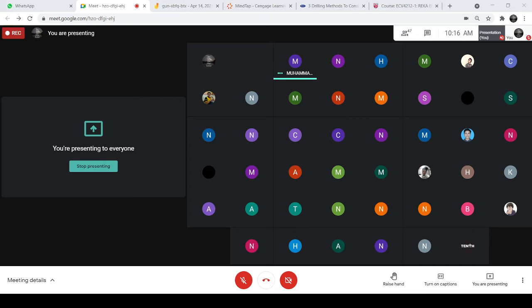The outside diameter is 66.68 millimeter, 82.55 millimeter, 101.6 millimeter, and lastly 114.3 millimeter. However, this boring possesses a few disadvantages, such as it is not efficient in loose sandy soil, especially at certain depth. Besides, it can only bore to a maximum width of 24 inches. And lastly, it does not do well below the water table due to water infiltration.